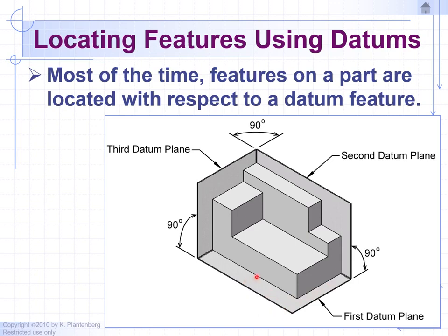Also, when machining this part, it'll start off as a rectangular block of aluminum, for example. And when you set it on the machine, whether it's a Haas or a Fadal 3-axis machine, to machine the part, the base is going to be touching the table of the 3-axis machine. So the base makes a good datum because it's going to be making contact with the table of the machine and most likely the part that it mates up to.